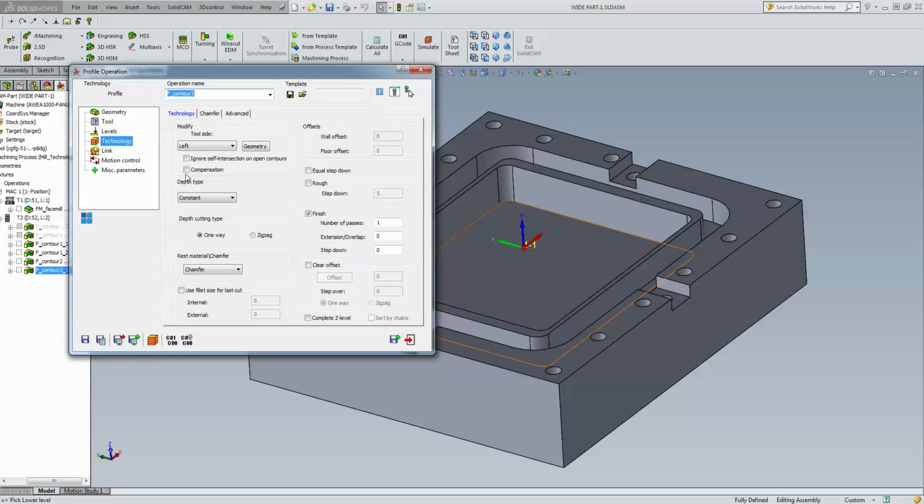If you need to make a change as far as the depth of the cut, in other words, you have a chamfer too big or too small, what I suggest is always just doing the adjustment on the machine as far as the depth of the tool itself. If you change the depth on the machine, you get to the right chamfer that you want, that will actually then work on any part that you have using that tool.